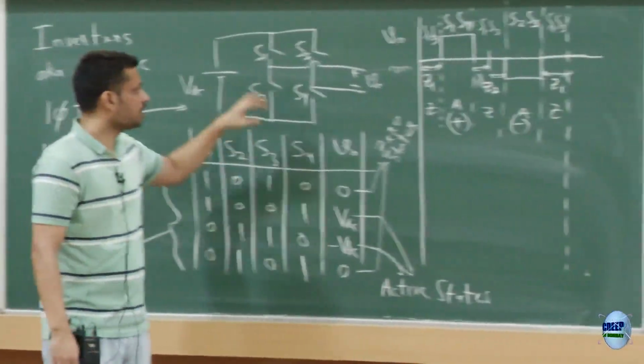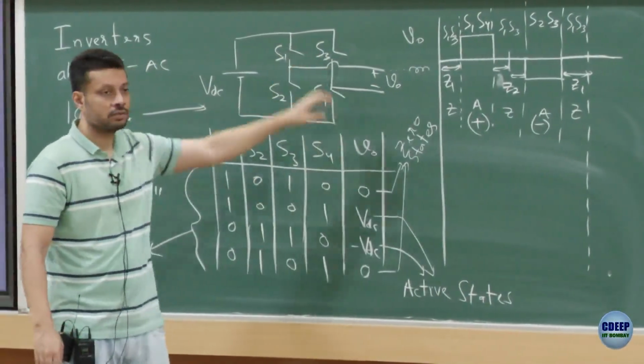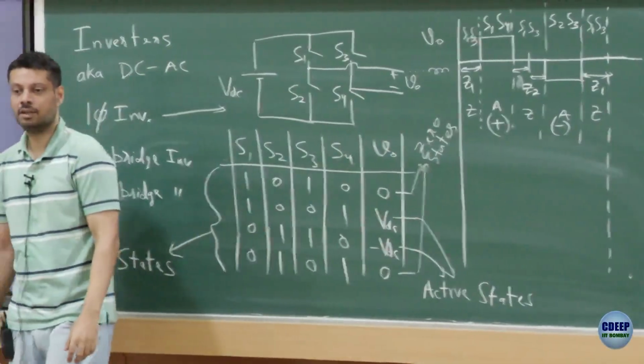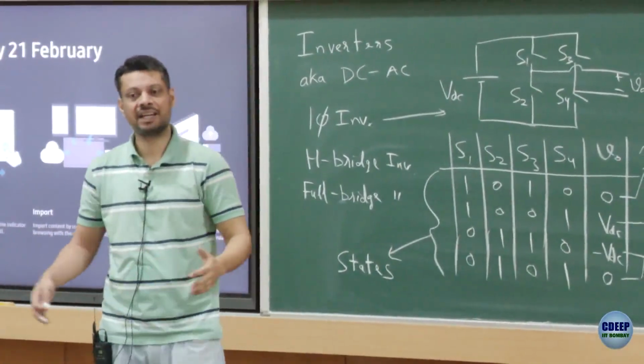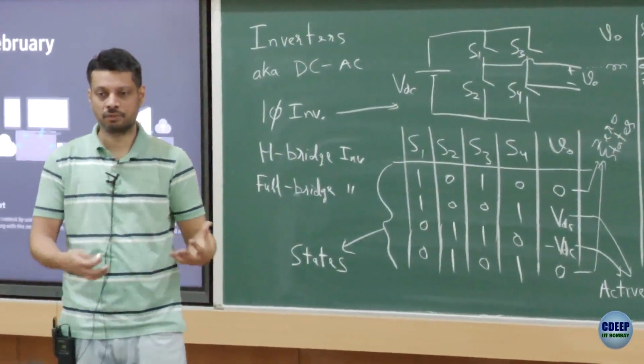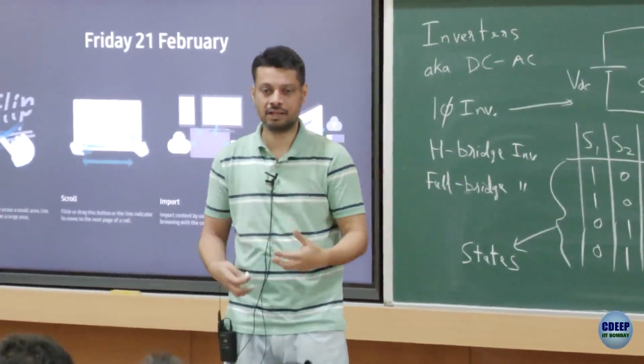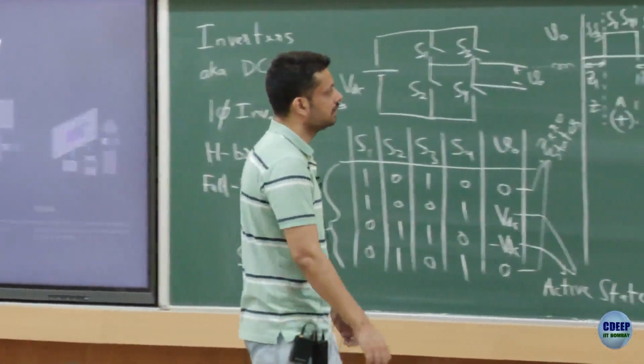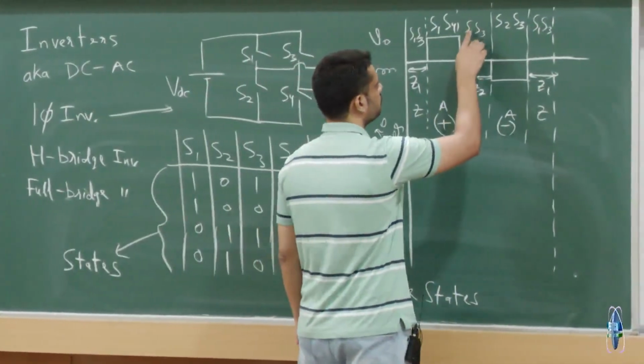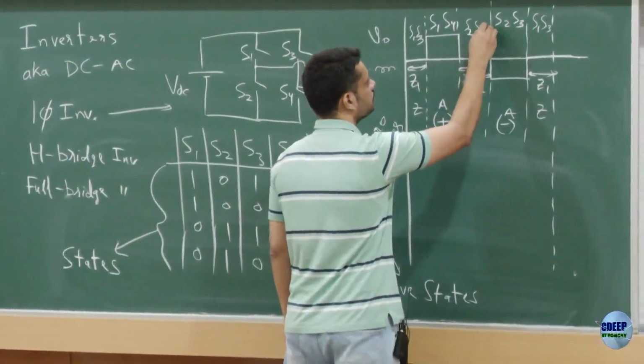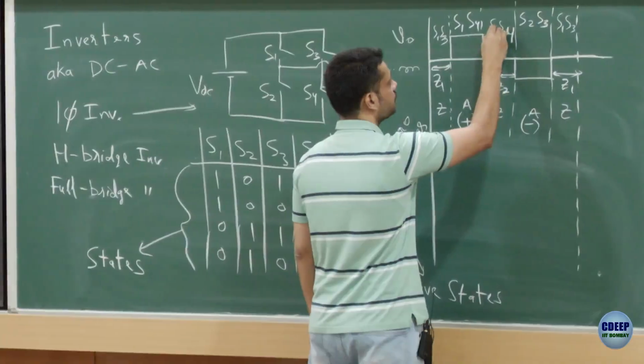Only thing is now your stress is not only on the two switches in terms of the RMS current. So the conduction loss is in a way getting divided also, because finally you have to cool these devices down and so on, right? A lot of those challenges. So, we can use S2, S4.